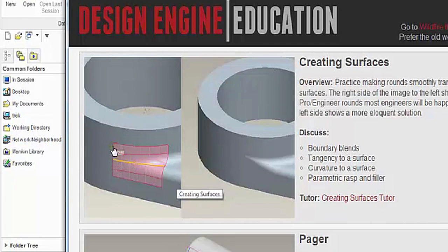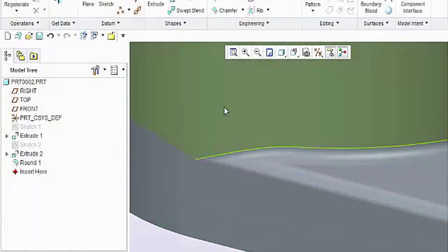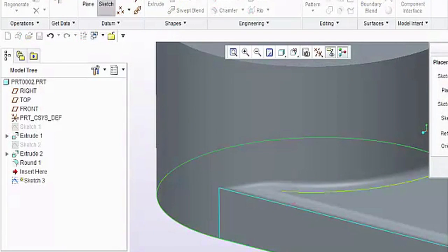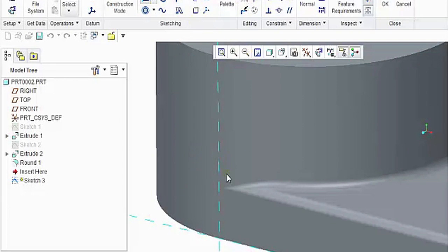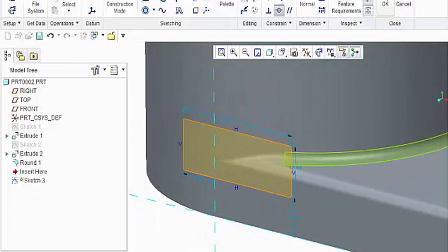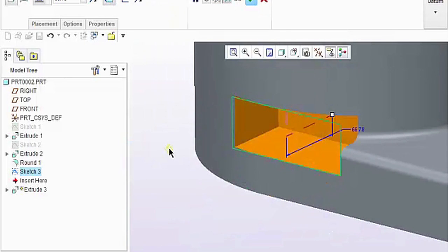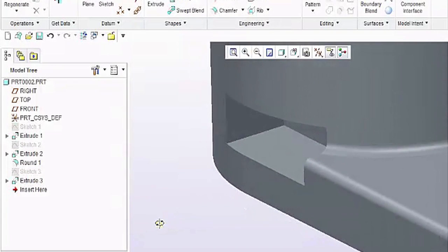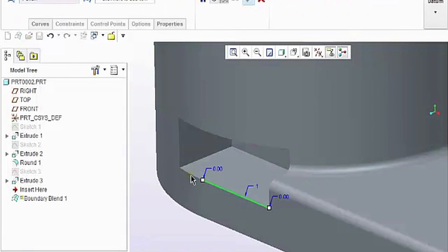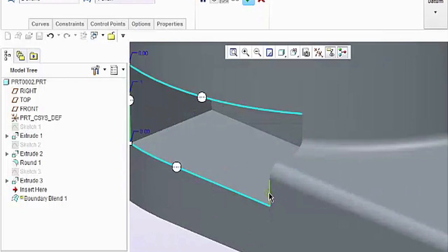I can diminish the round by building in a kind of patchwork. So I've got my geometry pointing to nothing. What I want to do is come up with a mechanism or a workflow that can cut this whole area out, and we're going to patch it back in using surfaces. So I'm just going to blindly cut out of this geometry a blatant hogged out cut, and I'm going to apply what I call the 5-minute fix. It takes 5 minutes to just get the rounds to resolve in a way that could be satisfactory just to go to tooling.